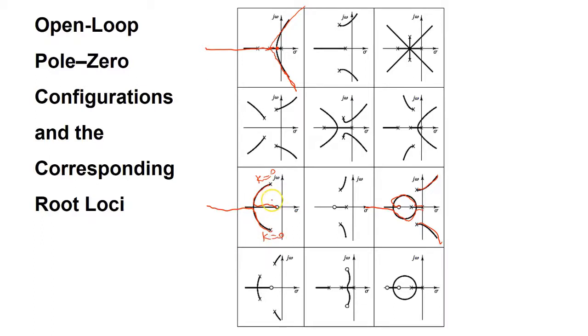And when k goes to infinity, you are approaching a what? A 0 of the g times h. But you might say, okay, this branch is just going to infinity itself, so where is the 0? You said when k goes to infinity, you should approach a 0. I can see it here, I'm approaching a 0, but what about this branch? Where does it go? It goes to an imaginary 0 at infinity. So we assume that there is a 0, but it's imaginary at infinity.